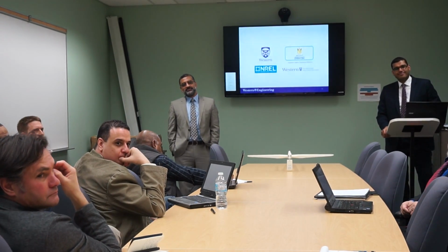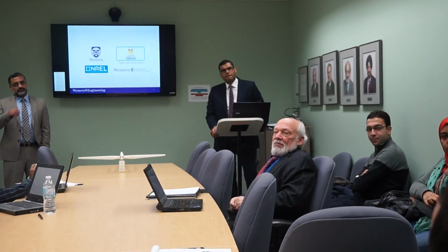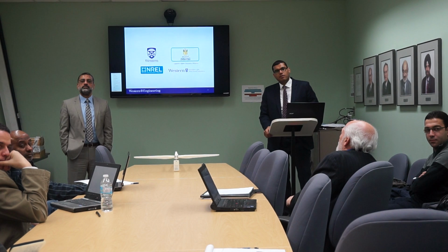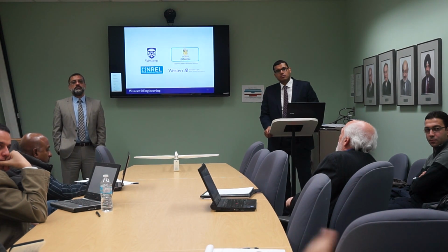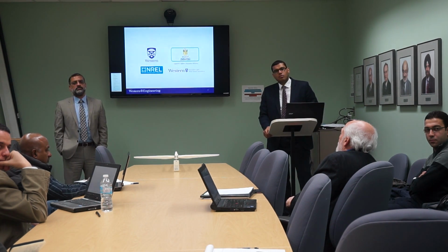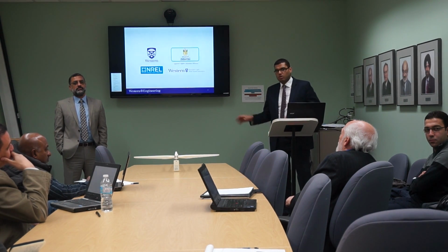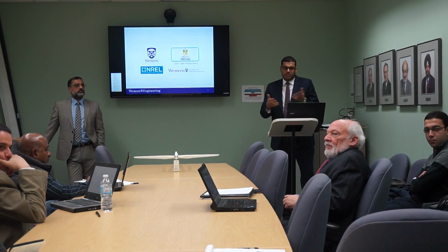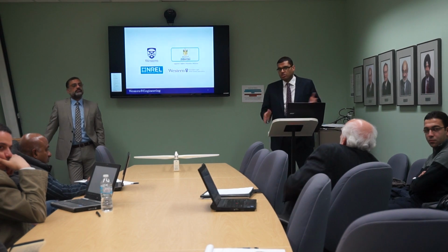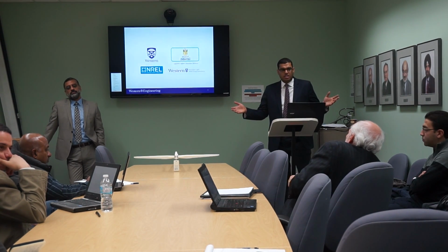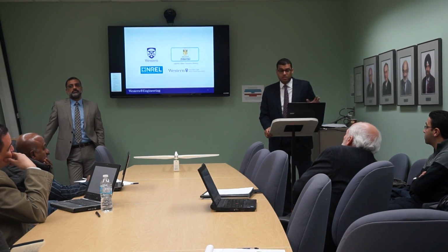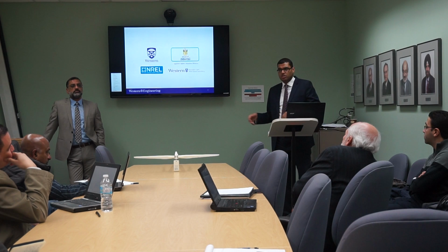What is the typical depth of the wind turbines? Of course, it depends on the type of the soil, but what is the average depth of a pile you can use, for example, here in this area and between here and Windsor? Between here and Windsor, it will be onshore, but our main concern here was offshore. For onshore, we have different foundation systems, so it will be cheaper to just use a gravity-based foundation system. Sometimes we use gravity-based with a smaller pile. But for sure, between here and Windsor, it's just onshore structures.